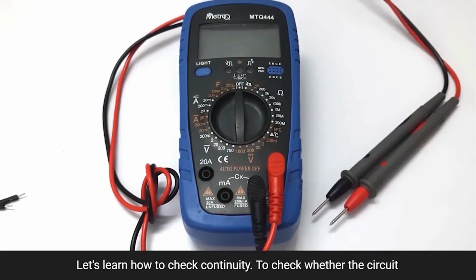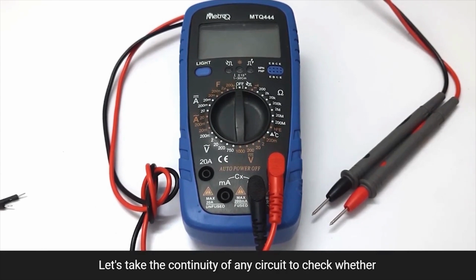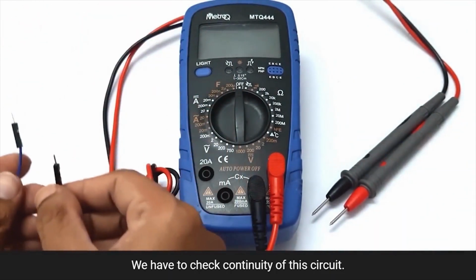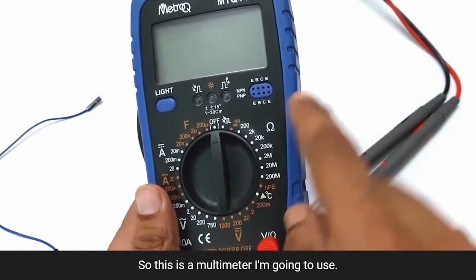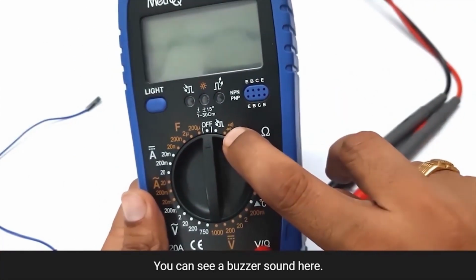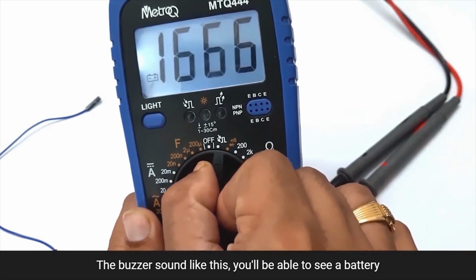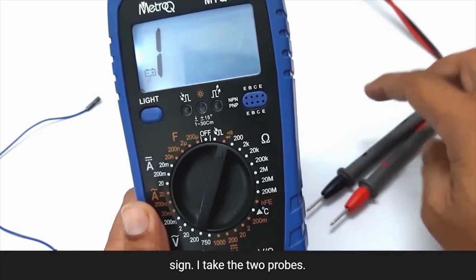To check whether a circuit is open or closed, let's check the continuity of any circuit. To check whether this wire is continuous throughout the line, we have to check the continuity of this circuit. So this is the multimeter I'm going to use. You can see a buzzer sound symbol here. We have to shift our knob to the buzzer sound like this. You'll be able to see a battery sign.